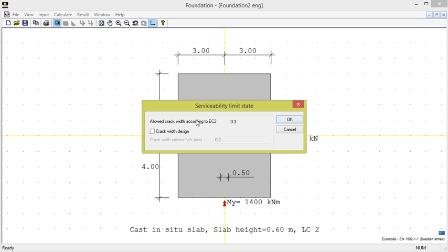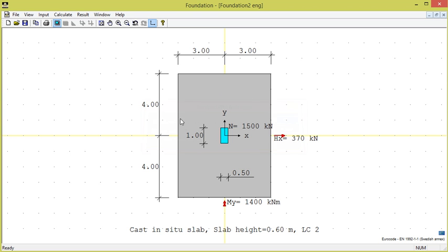Here the allowable crack width is shown, in case such conditions were defined previously so that such a requirement exists. We see in this case that the code requires a maximum crack width of 0.3 mm. We will return to this as well as the option settlement later.